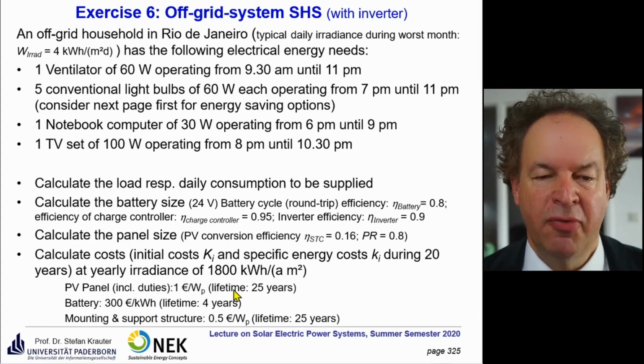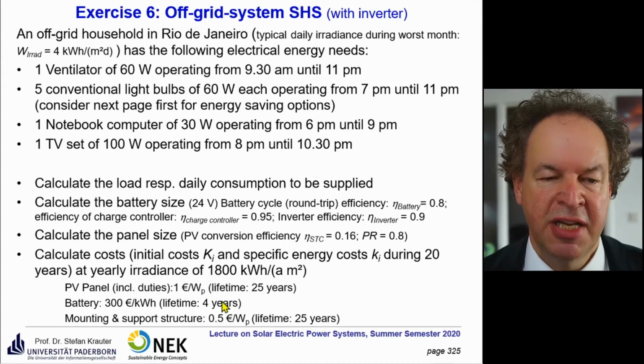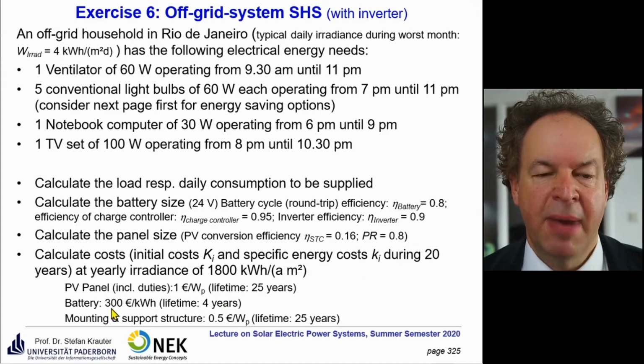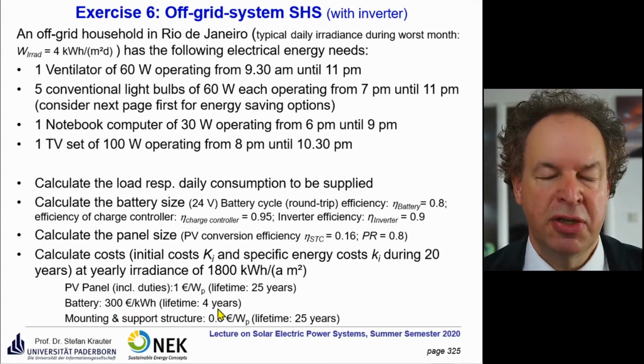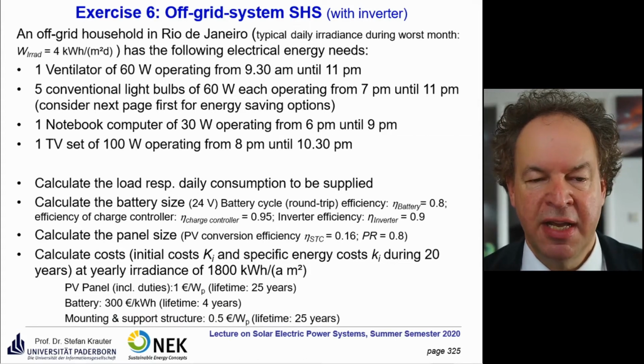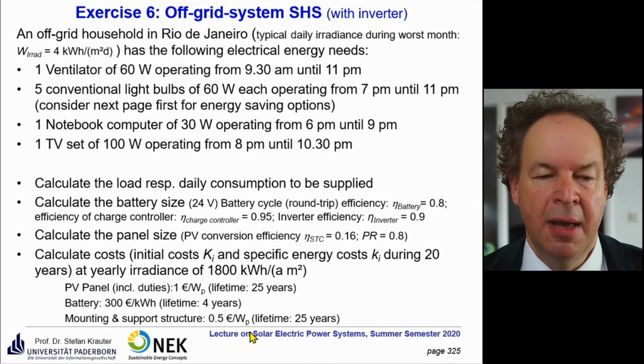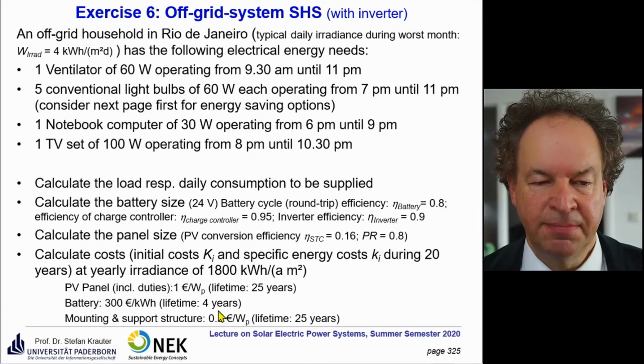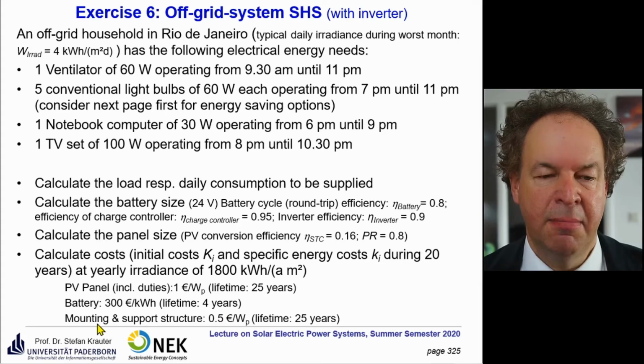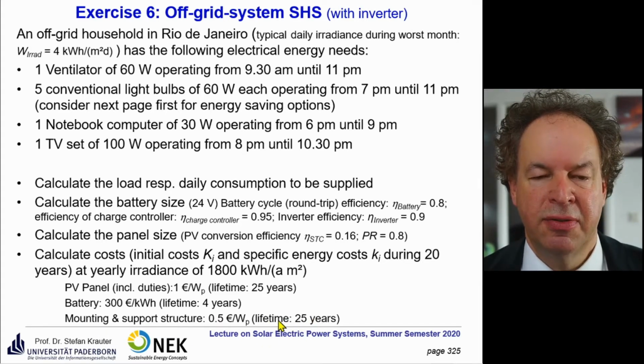And a lifetime of 25 years. So during 20 years is 25 years, we don't have to exchange that. Opposite to the battery, which has a lifetime of 4 years only. That's also due to the elevated temperatures there. We have to exchange the battery relatively often. And the mounting support structure, which also has a scheduled lifetime of 25 years, we calculate with €0.5 per watt peak.